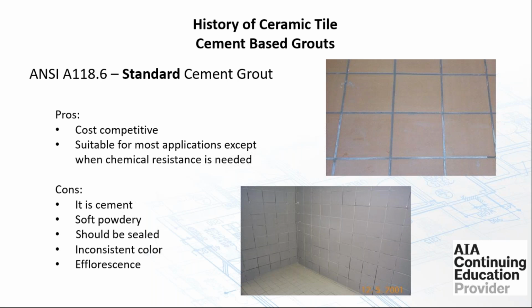The other thing with the Portland cement grout is that it is prone to having efflorescence. In the curing process of the grout, the cement produces a free lime. That free lime, as water gets into the grout, is brought up to the surface of the grout. Water evaporates, and that white chalky residue remains, your efflorescence. This is a problem with a Portland cement grout, and it can happen after the grout's been installed because of rain or excessive mopping of the floor, or it can happen right after it's installed because too much water was used in the mixing of the grout or the cleaning up of the grout. But the efflorescence can be a problem with these grouts.